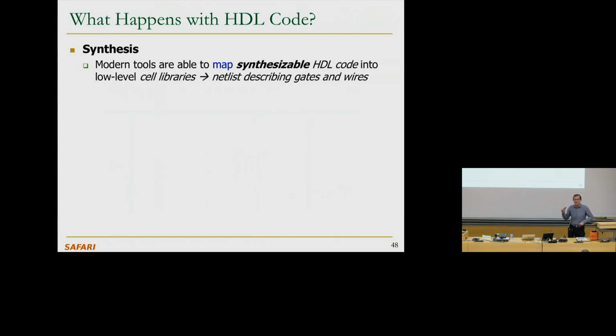If you do gate-level structural Verilog, everything's synthesizable. Most of behavioral Verilog is also synthesizable. But if you go fancy, it may not be synthesizable. Because now your tool needs to actually figure out what kind of low-level circuit it needs to generate based on the description you have, right? You have some hardware description. So somebody also in the break asked the question, will the circuit that's generated by the structural Verilog code be the same as the circuit that's generated by behavioral Verilog?